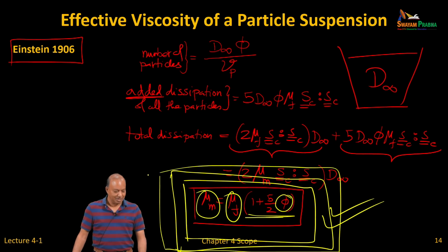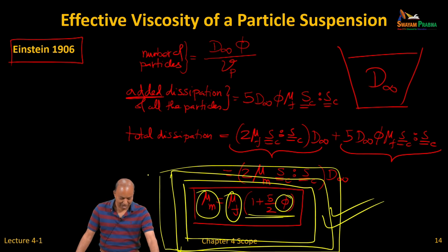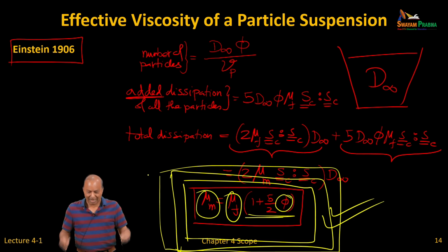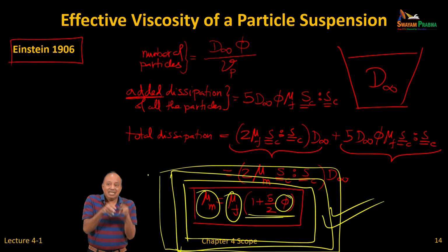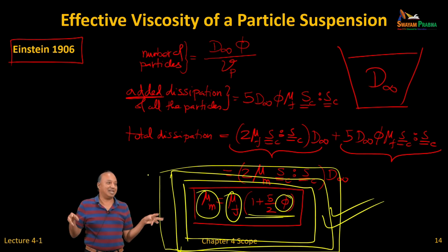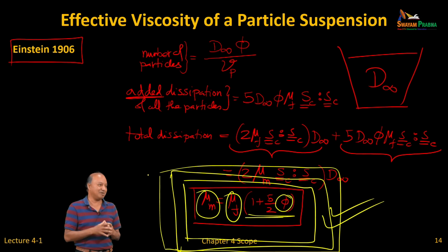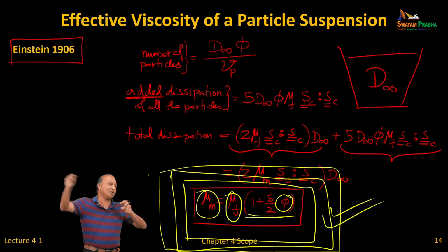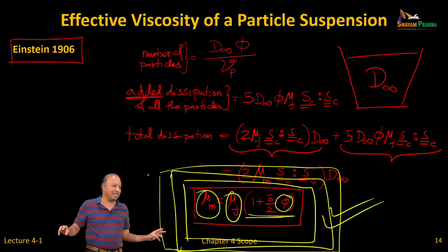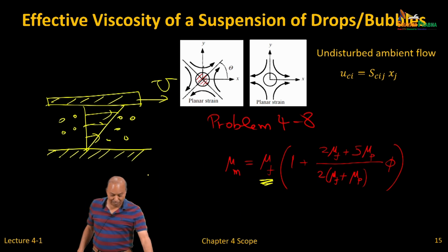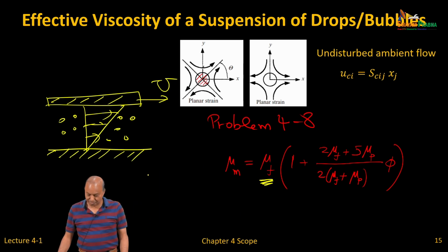Now what happens is, at the level of micro scale, each particle is creating a stresslet. Every particle is creating its own stresslet, and you add them up, they all increase the viscosity, and that's why the stresslet is a very simple solution. And this works only when the particles are far away, and therefore good. When the particle volume fraction increases, then it gets very complicated.